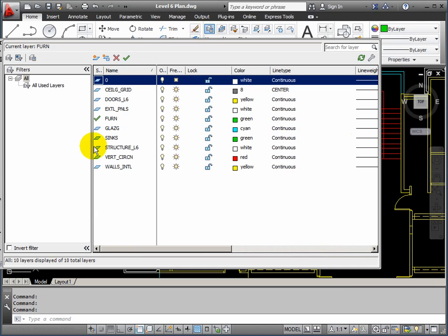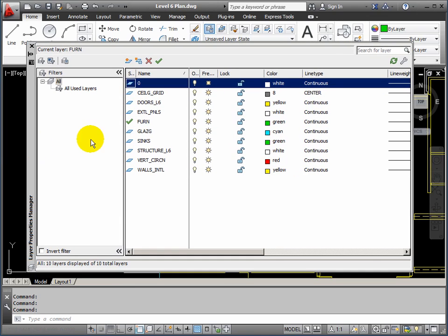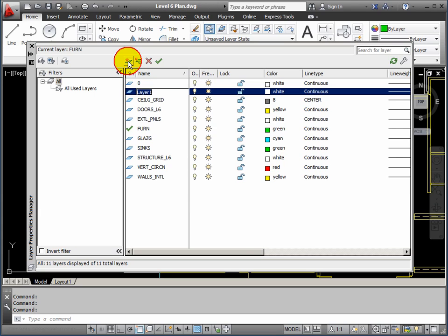The dialog box is a wee bit big here. Let's make it a little bit smaller. I want to create a new layer, so I use the first icon on this list, and I'm going to call it areas. I want to choose a color that will end up colored red. I'm not going to use this one. I'll need to explain this later on.